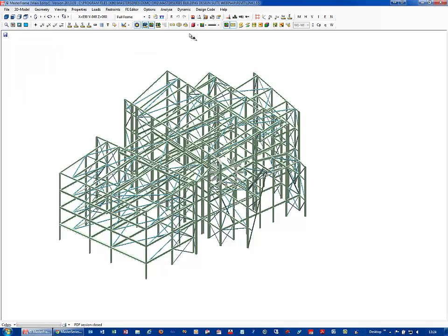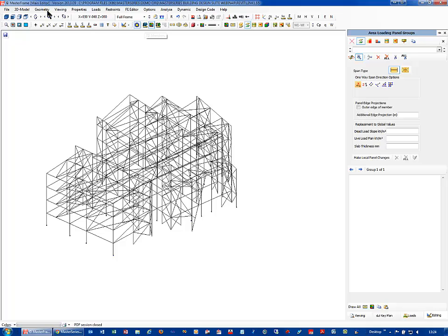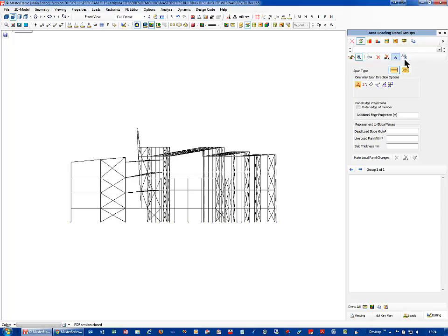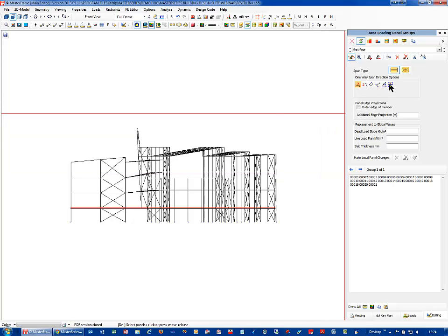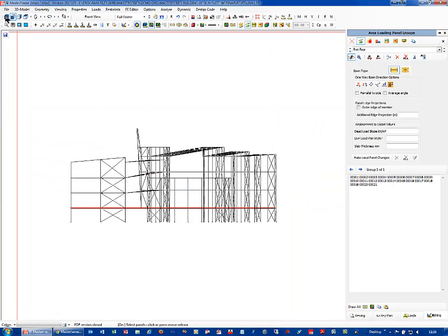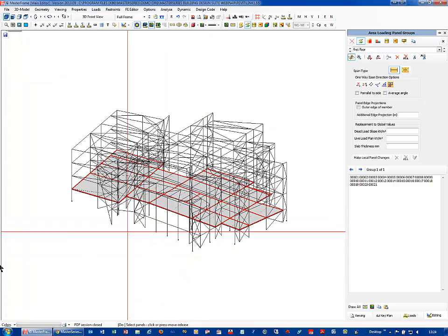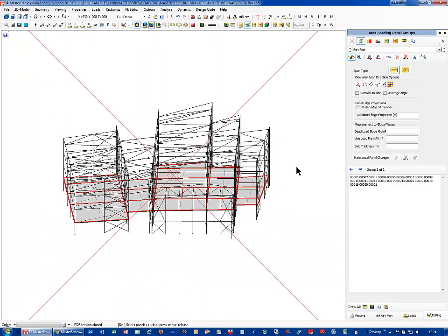and I'll just slip back here to wireframe. It's just easier. I'll put it in the front view, and the first one's going to be called first floor, and I'm going to make this in apply mode to be all these, and I want to make it shortest, in fact, so they will all be shortest. So that's the loading done on that floor,